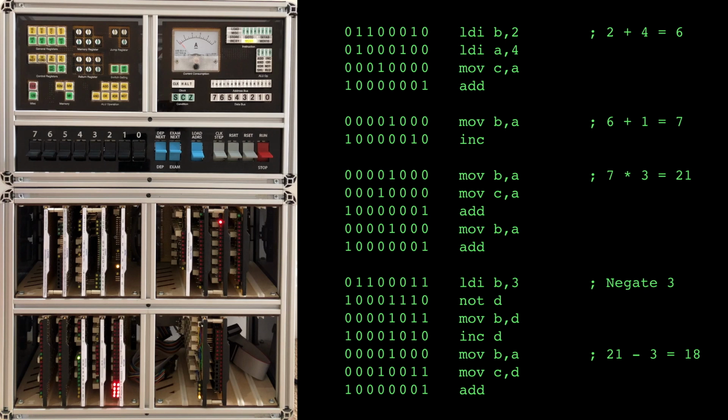This allows me to demonstrate the 3 instruction classes that the computer is capable of so far, which are SETAB, MOV-8 and ALU. In the left column are the binary opcodes which I'll be entering into the computer, followed by the equivalent assembly mnemonic, and finally at the end are any comments. So let's crack on and enter the program into the computer.